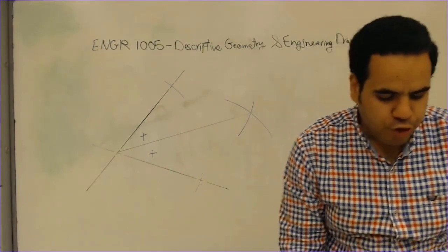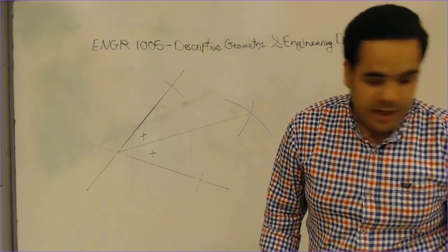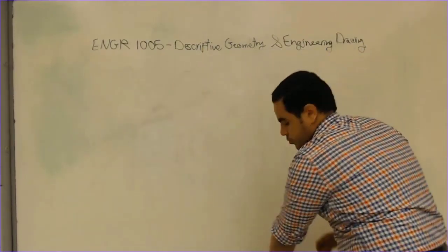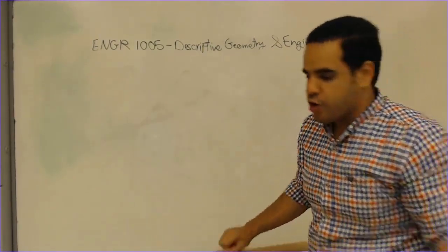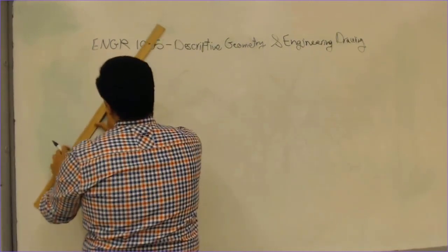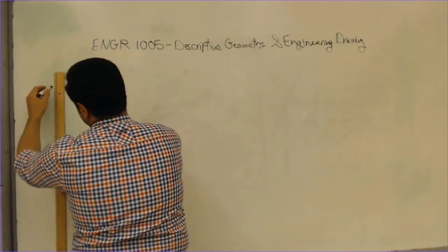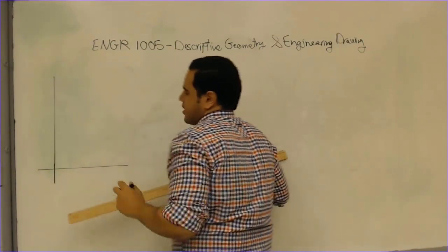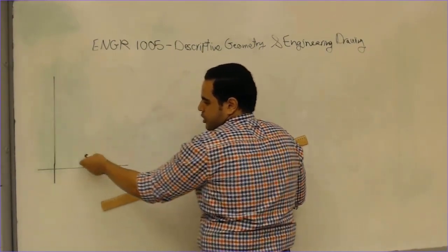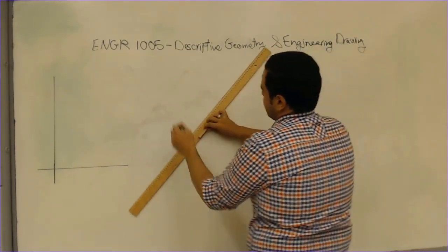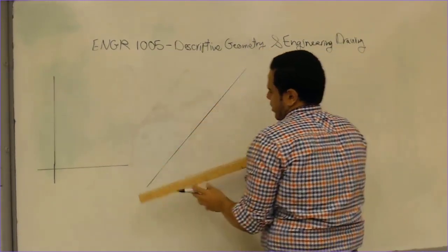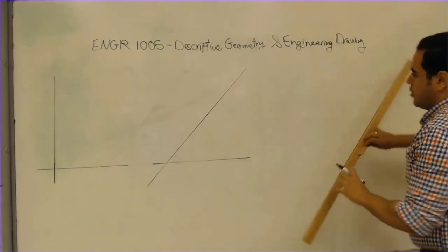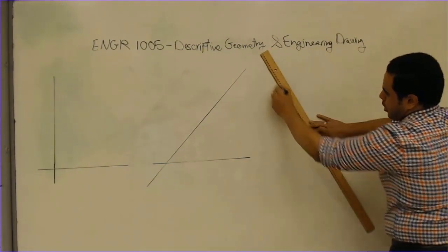The following rule is how to draw a fillet. What is a fillet? In a minute, I'm going to show you how to draw a fillet. We have three different cases of drawing a fillet. Whether you have a normal angle like this, which is a special case, and the fillet is to draw a tangent arc between these two lines, and the second one is with an acute angle, and the final one is how to draw an obtuse one.